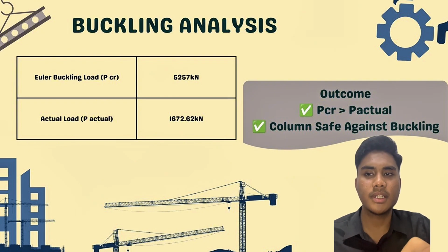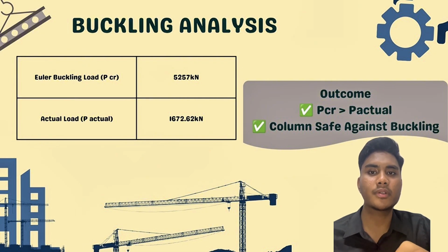Based on the calculation, the critical buckling load, PCR, is 5,257 kN. The actual load acting on the column is 1,672.62 kN. Since the critical buckling load is much greater than the actual load, the column is considered safe against buckling. Therefore, the selected column size and support condition are adequate to resist the applied compressive load.